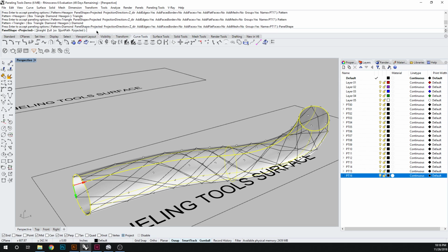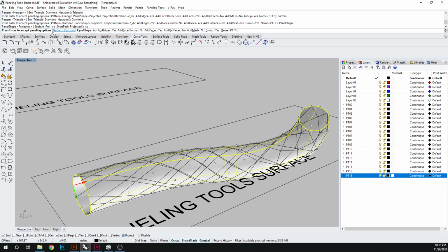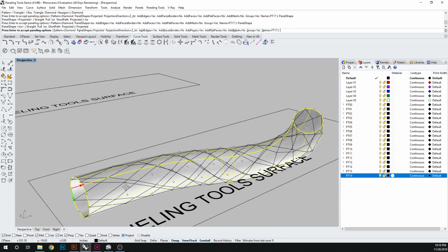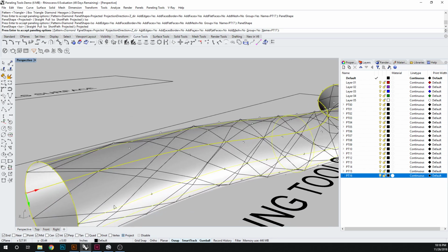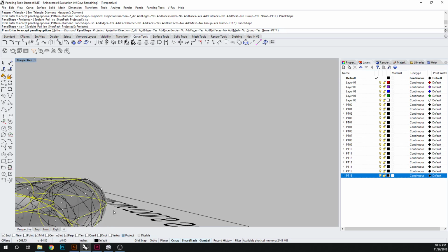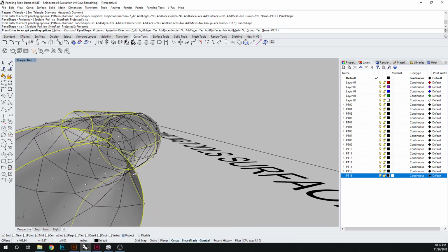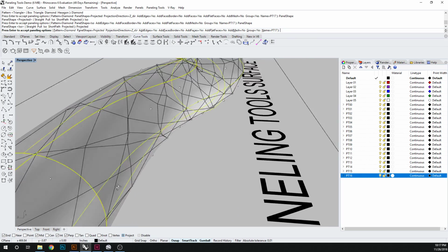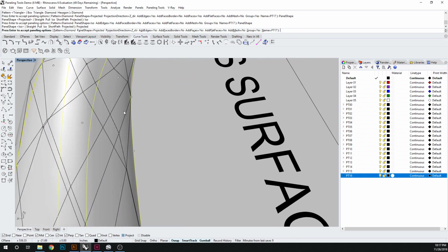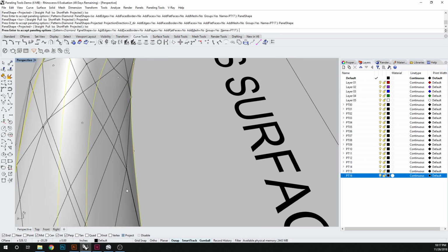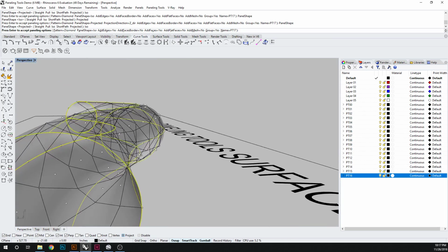And there's a variety of other bits up here. So the shape, whether it's pulling from an ISO curve, or if it's straight, or if it's the shortest path, or it's projected. So this happens to be how it draws the curve. Is it on the surface, or does it find the closest path? You can determine this, sort of experiment with how they work. When you're looking at them, you can see that it sort of bends around it. So if I do an ISO curve, it should stick on the surface better.